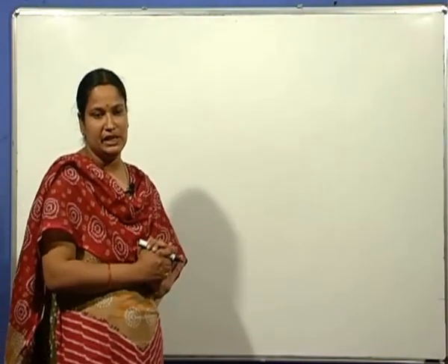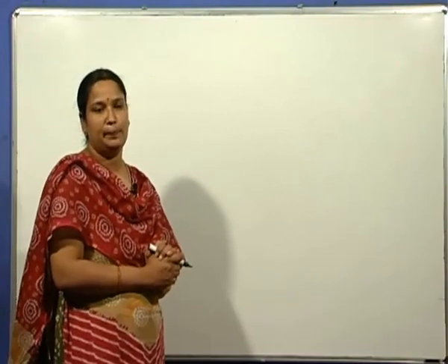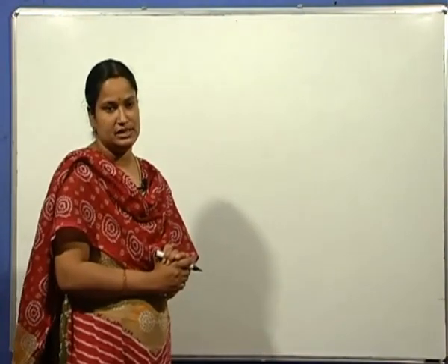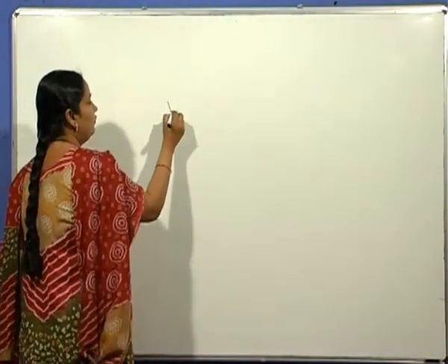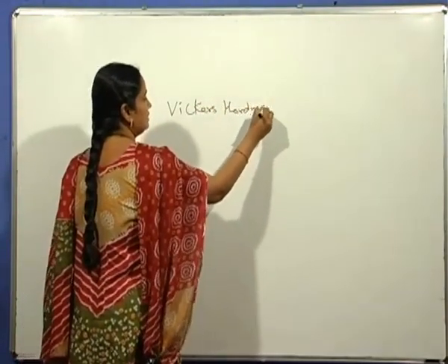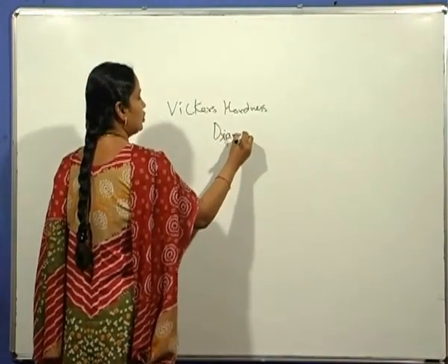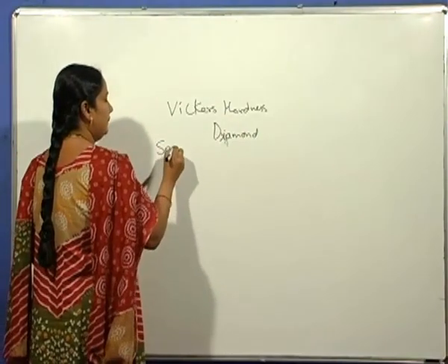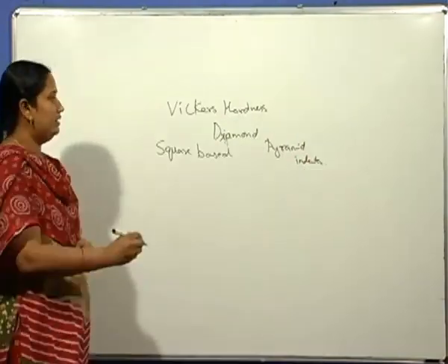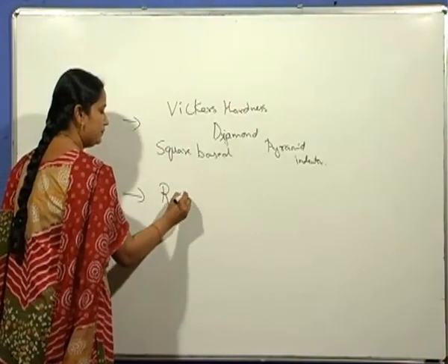As there are certain limitations in the case of Brinell hardness, this prompted the development of other indentation methods. The other indentation methods are the Vickers hardness test, which uses a diamond pyramid indenter, a square-based diamond pyramid indenter, and another indentation hardness method, Rockwell hardness.